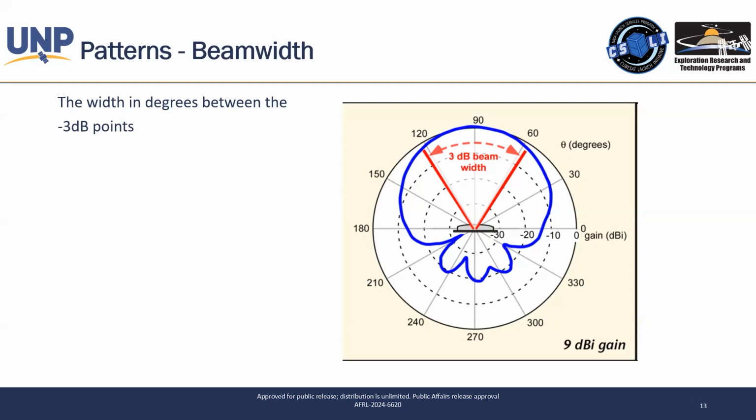Typically the more directional your antenna goes, the more you focus that electromagnetic energy, then typically your dBi is going to go up, but your directivity is going to go down. And so this is an important design decision, because you have a satellite that could be tumbling up in space. If you have a highly directional antenna, you just hope that the boresight of that antenna is pointing at your ground station at the exact moment you want to talk to it. That's not a very good guarantee.